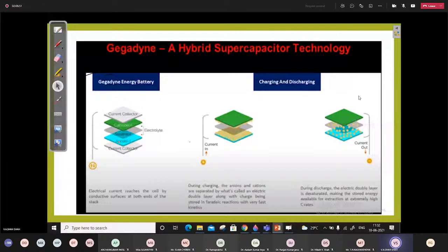And the battery current at 48 volt with UC, that means it has to supply only 1.143 kilowatt. So it is nearer to 23.18 ampere. And so 5 in parallel and 12 in series to maintain the same voltage level. And the supercapacitors will supply a maximum current of 86 ampere. The Maxwell 300 Farad, as I have told you, can supply 100 ampere current. And the voltage is 2.7 volts. So 18 supercapacitors must be connected in series. No parallel connection is required to support this.